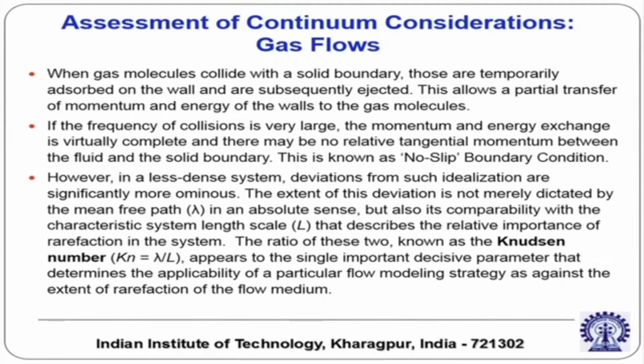Then we assessed the possibility of slip boundary condition for gases, and for gases our general conclusion was that if the number of collisions or the frequency of collisions between the gas molecules and the solid boundary is sufficiently large, then there is almost a perfect exchange of momentum and energy between the gas molecules and the solid boundary. So, if the solid boundary is at rest, the gas molecules in the vicinity of the solid boundary will also come to rest, and that is known as no slip boundary condition.